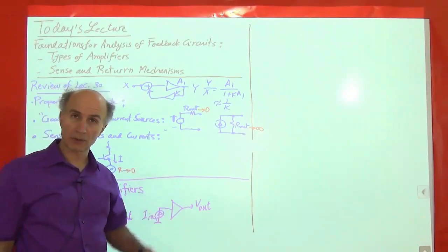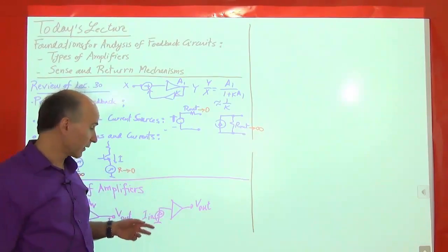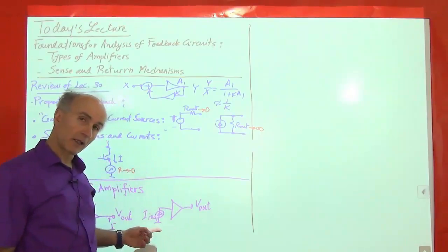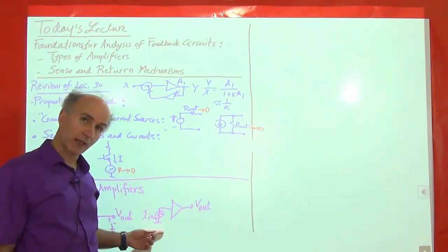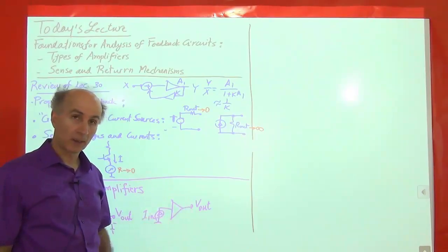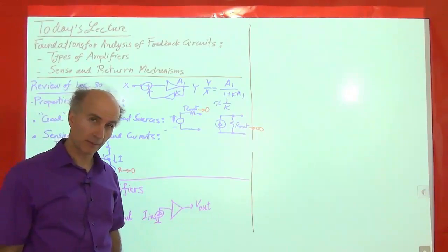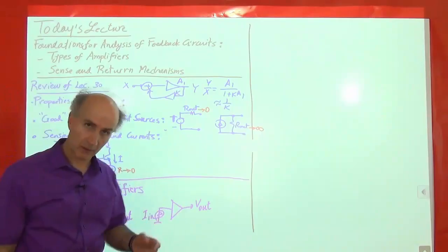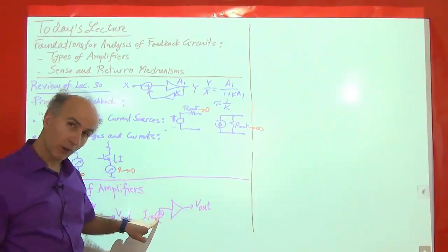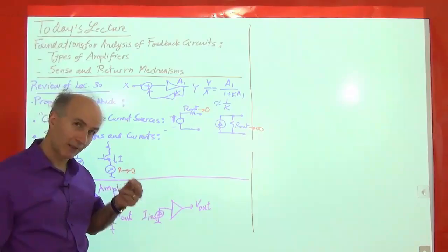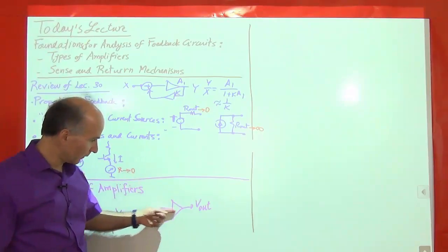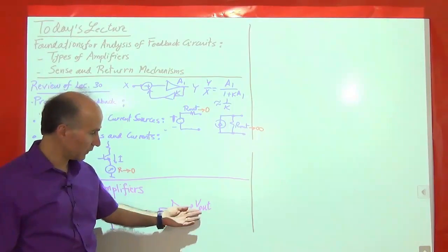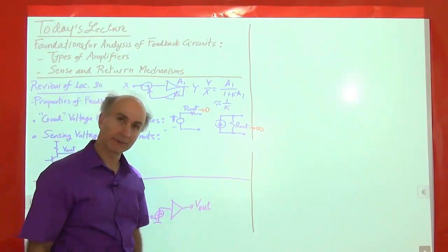So again, without going through too much trouble, most of the cameras, in fact, the camera that is capturing my image right now, in its sensor has a current for every pixel, and that current has to flow through an amplifier like this. In optical communications, we have the same situation. So in some applications, maybe 20% of applications, we have a current quantity representing the signal of interest. And that current has to flow through some sort of amplifier and eventually give us a voltage. We would like to have a voltage because processing this voltage is easier, right?